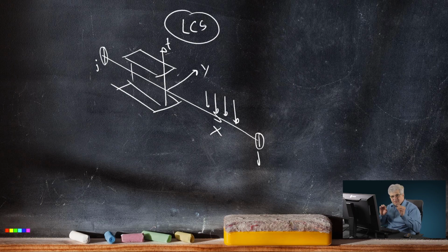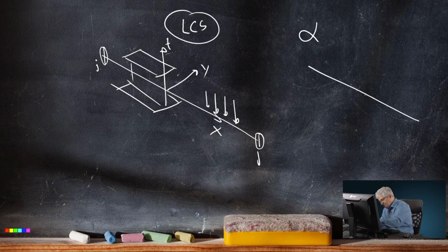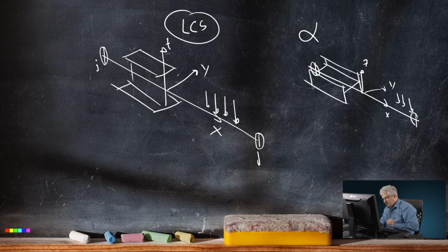If you rotate with the alpha, what happens? We have the beam. The coordinate system remains in the same position, also the loads, also the hinges. Only the cross-section will be rotated. This will then be my cross-section. Everything stays in the same place.